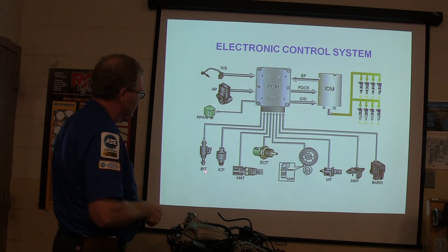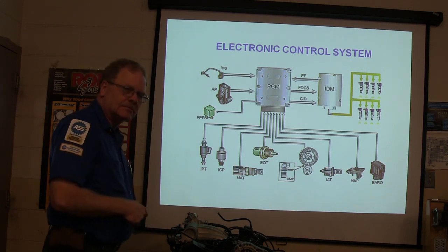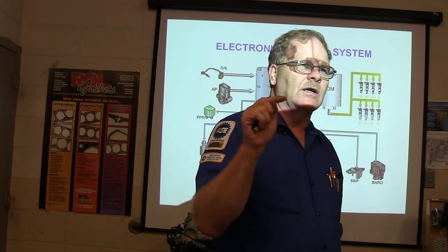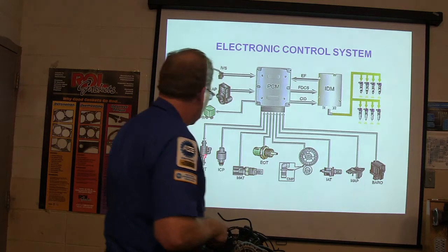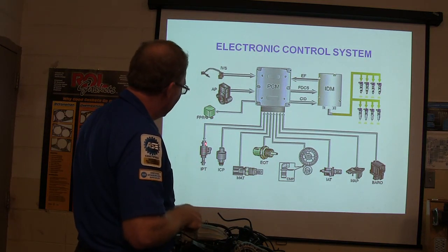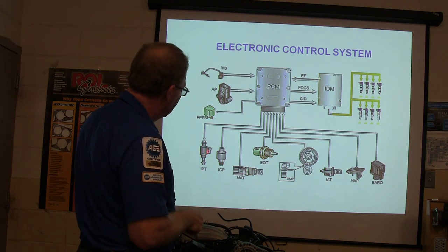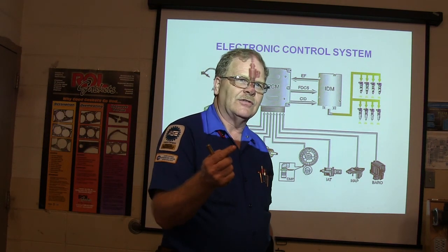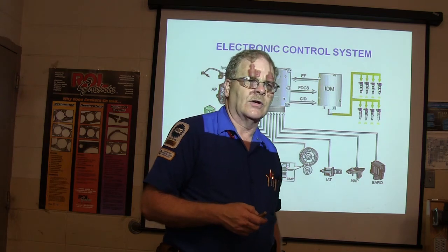What's this right here? That's an injector. Yeah, this is not an injector, this is the injector control pressure transducer, the IPT. All right, so basically that thing right there is an output. And as it puts more current to there, it's actually gonna increase the injector control pressure.